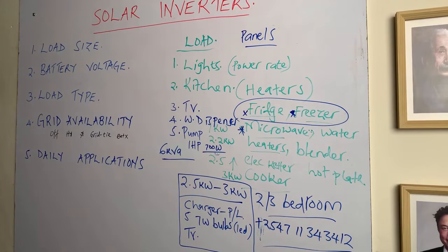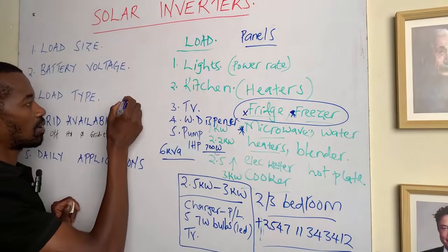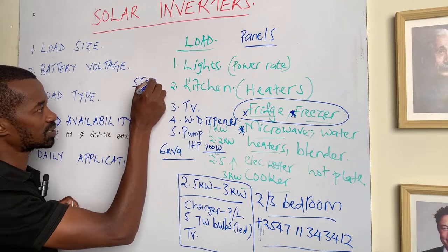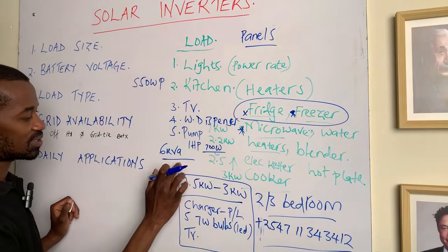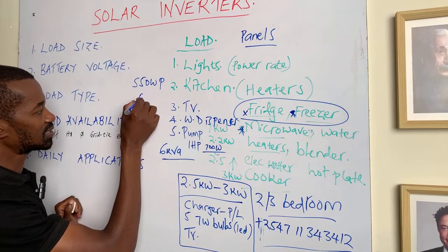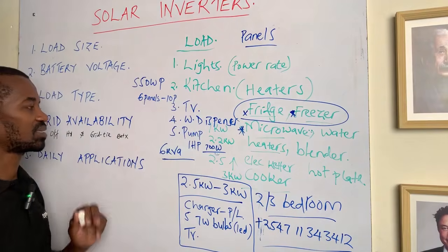Again, it also comes to the individual wattage from the solar panels. Assuming that these solar panels are, let's say, 48 volts or 50 volts, that is the open circuit voltage, we need to understand that we need to know the number of panels that we are going to use. Assuming it is a 550 watt panel off-grid system for a 6 kVA, we definitely require around 6 panels to 10 pieces, 6 to 10 pieces, all right?